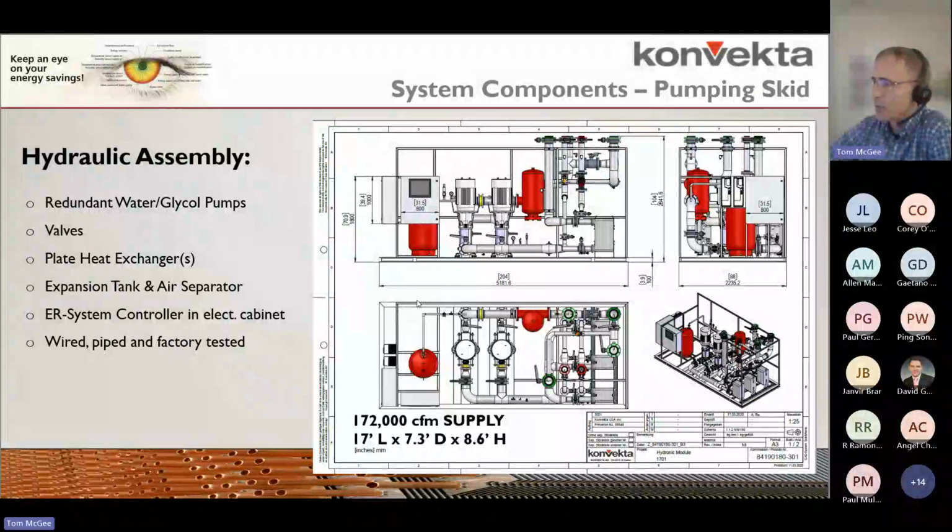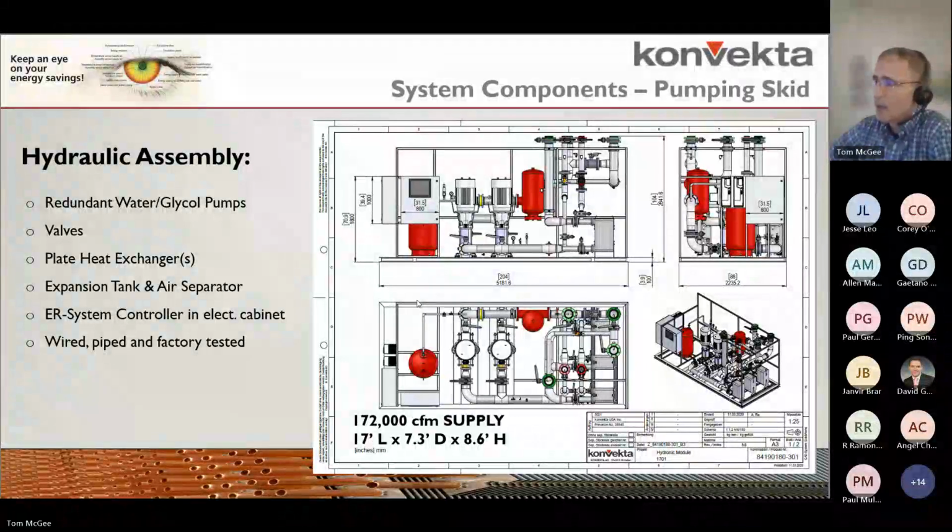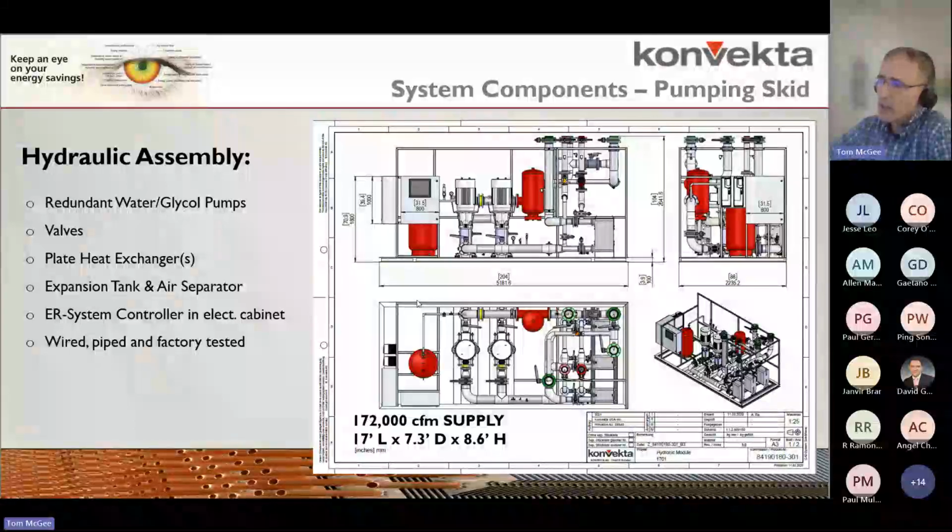This one, we've got heat exchangers in the list on the right, we've got all systems that we install here. We've got pumps. It's 100% redundant inline pumps, and our standard is Grundfos. So in addition, any valves that we can incorporate into the fabrication of the skid, we go ahead and do that.